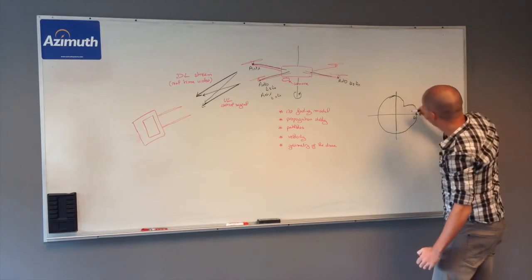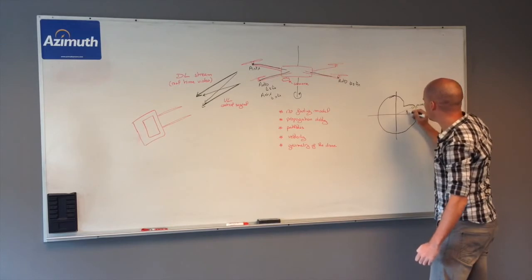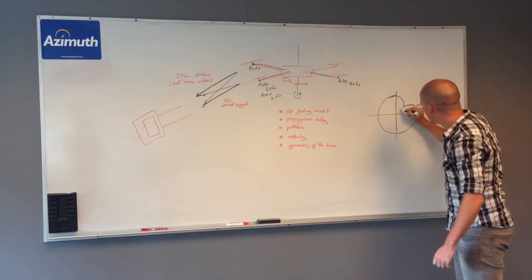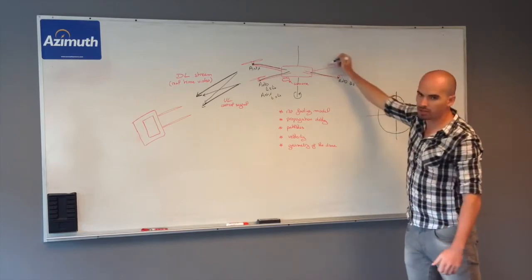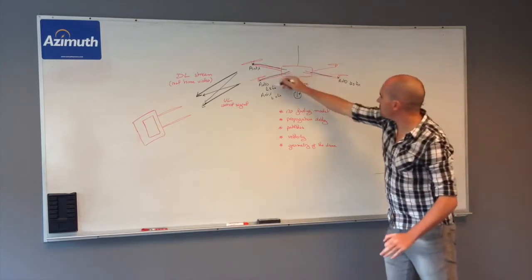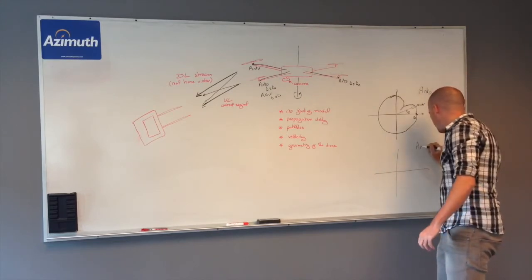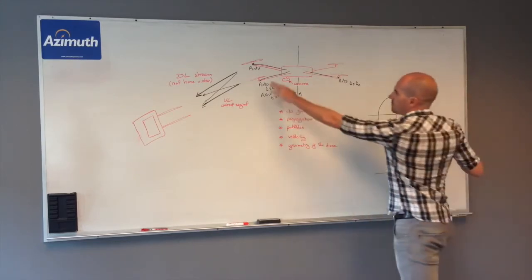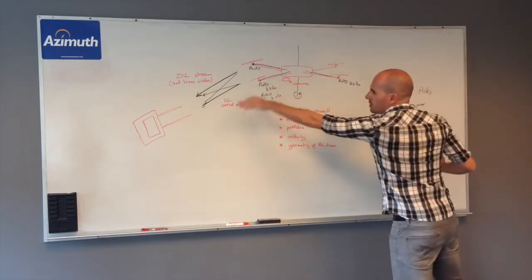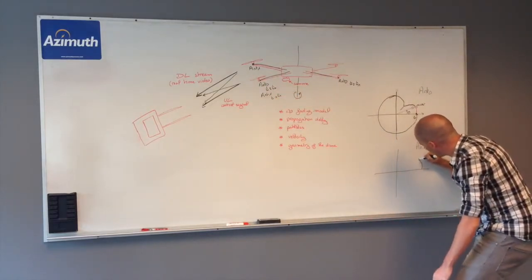So actually, if you imagine this is the power value, and this is the angle during the rotation. We have to deal with a situation where we have a drop of the signal in one antenna at a time. Because if now we take antenna 1, we just did it for antenna 0, and we do the same thing, we'll see that when this one is hidden, the other one is here, and still has the line of sight to the radio controller. So the power will still be strong enough.